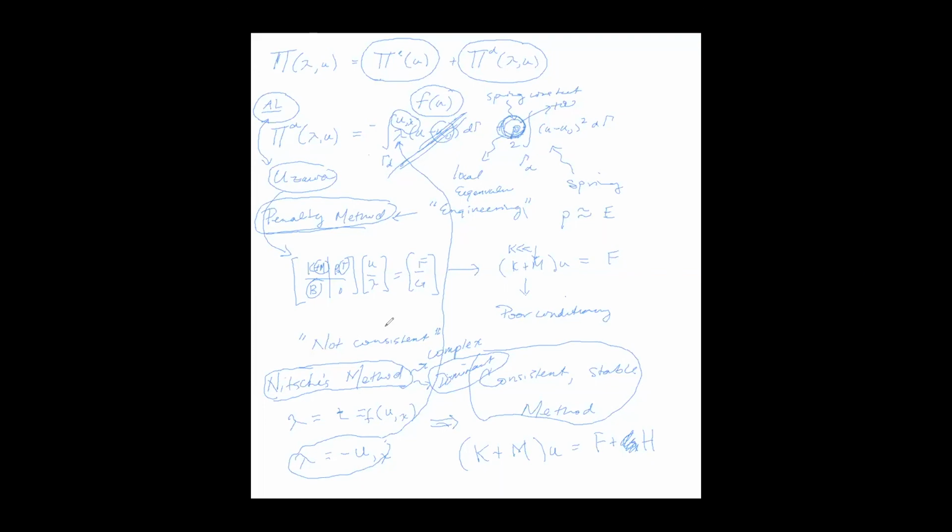Okay, so that gives you a 10,000-foot view of where spline-based simulation is in the enforcement of boundary conditions. Of course, there are approaches where you simply set nodal values. That still is done as well. That's just a standard approach, and that is still a part of the toolbox that you have available to you as well.